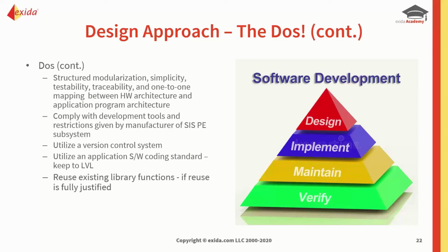The other thing is, if you're using development tools, we have to comply with any restrictions that are provided by the manufacturer of the programmable electronic subsystem. So here again, as I've said, most of the time the logic solver guys will provide you with tools, and you need to make sure it's understood how these can be used, if there are limitations, what they are, and note that. We should be following a version control system. And again, some of these things you think, well, isn't that obvious? Well, I can tell you for now, that's not that obvious.